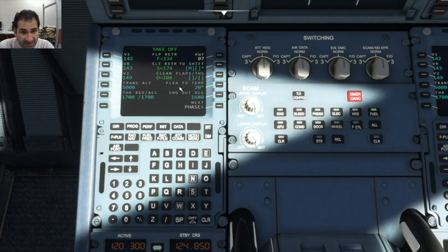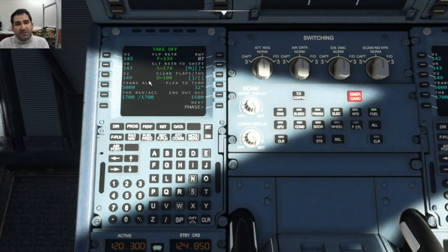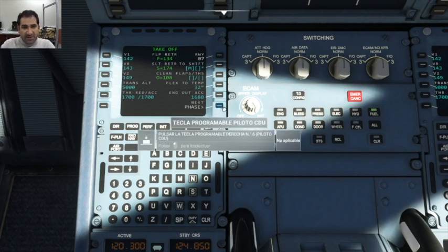and then here's the flex temperature. Okay, the flex temperature in our case was 32 degrees. This is just to cheat the aircraft and to tell the vehicle that temperature is higher than existing ones so that you get more power. And we can click just here next phase.